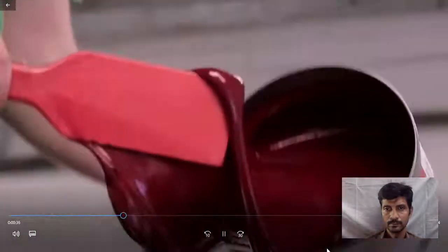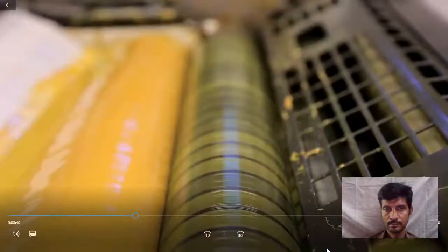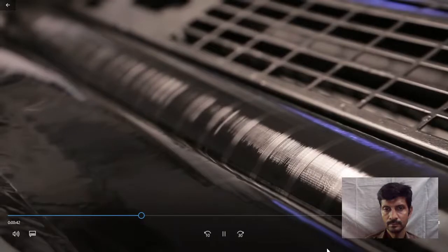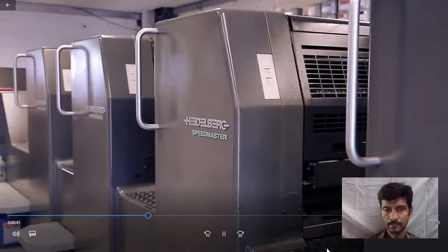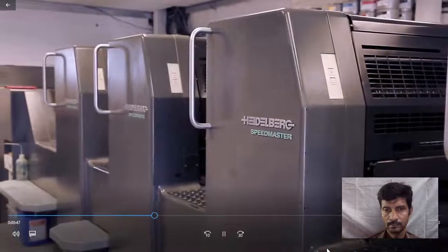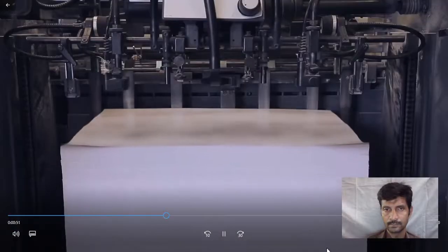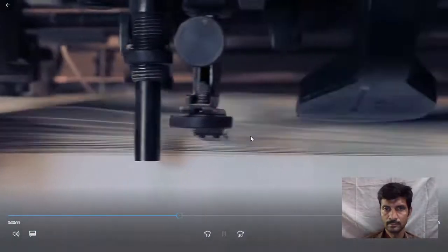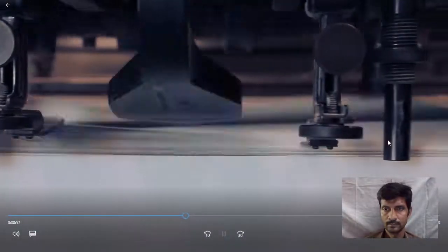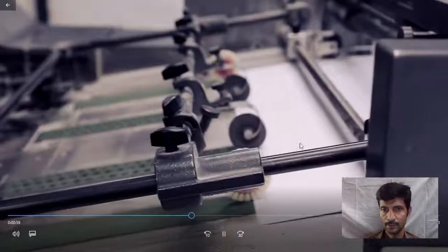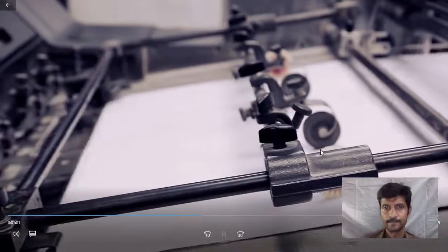Color printing typically uses ink of 4 colors: cyan, magenta, yellow, and black. The color model is CMYK. For this job, we will be using 4 of the printing units. The stack of paper is lifted into position. A sheet separation unit separates the paper with jets of air or a vacuum to ensure that only one sheet is sent through the press at any one time.